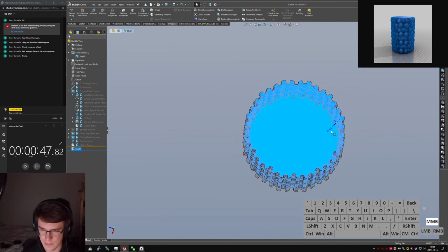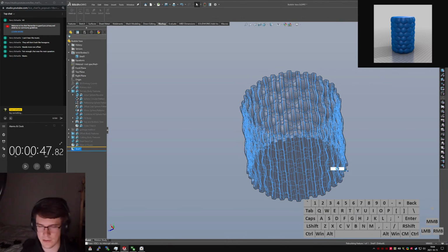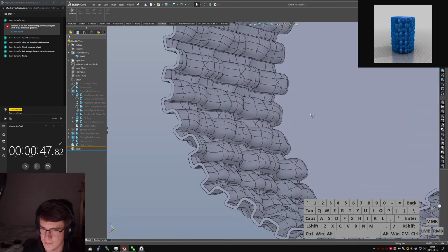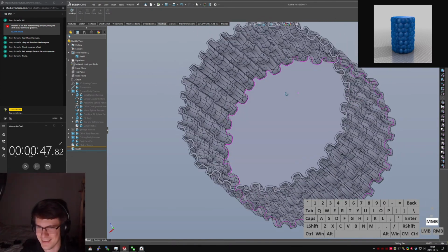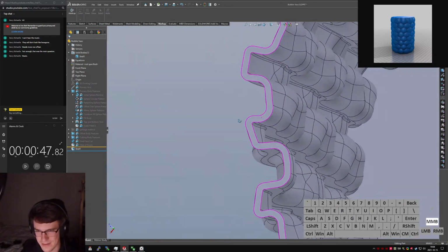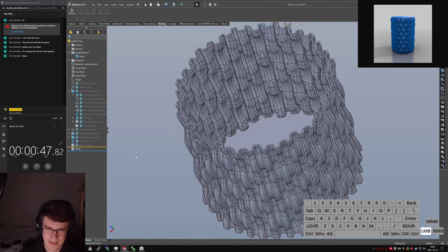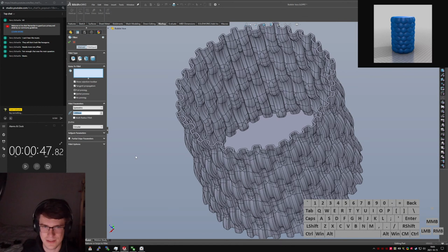So we take this shell. 0.8, and that'll make it crunch for a bit. This thing's not going to print well at all. Real funny to watch it try, though. Oh, I want those fillets a little bigger, just so we don't have quite so tight corners on the inside. Let's do 1mm and see if I can click that face and make it, maybe it won't explode.